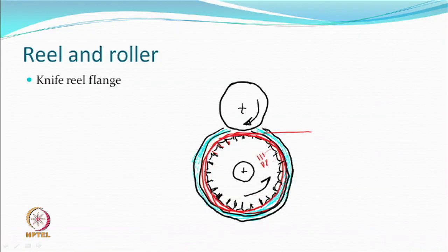So wherever the pressure is high enough, you will start getting fibers coming out. So the staple length, etc., is decided by this so-called roll, and this is a continuous process, and you can suck the material from inside and take it to the baling press.